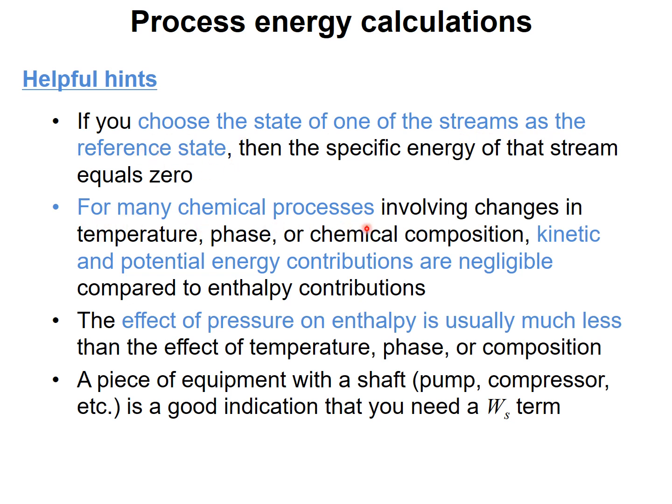For many chemical processes, I'd like to emphasize chemical, involving changes in temperature, phase, or chemical composition, kinetic and potential energy contributions are negligible compared to enthalpy contributions. So, in most chemical processes, you don't need to think about the kinetic and potential energy terms.